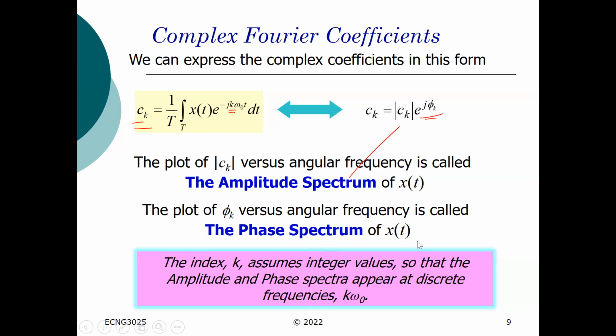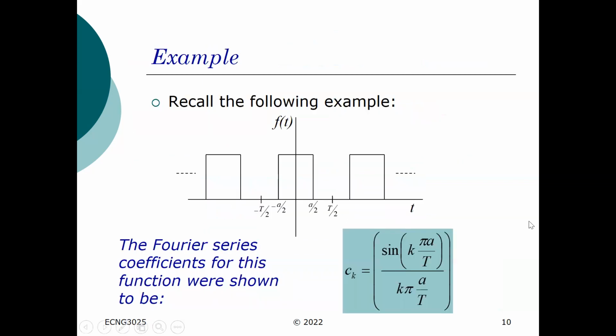All right, so a continuous time periodic signal, when you do the spectrum, has discrete components. And the discrete components occur at multiples of their fundamental frequency. All right, so that's an important thing. And we saw it here. We took a rectangular wave. The period of the wave was T, and the actual duty cycle was determined by the pulse width here.